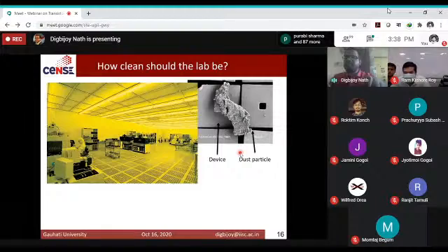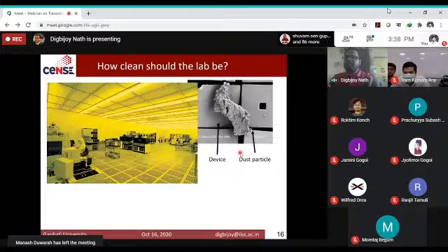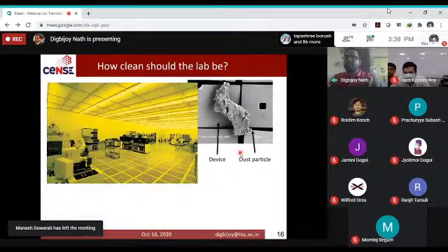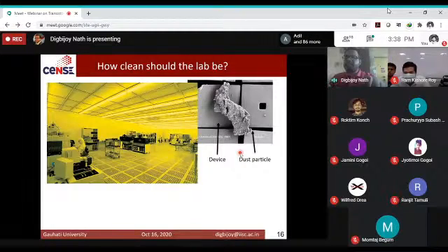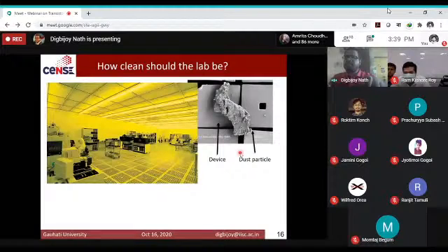That substance is sensitive to photons of higher energy. For example, in visible light, in surrounding sunlight or tube light or bulb, you have light of also higher energy, like the blue component that you cannot see, of course. That will damage those chemicals. That's why you should use a longer wavelength light. Now, red is the longest wavelength light. So ideally you should use a room whose background lighting is red. But then alarms are also red. If there's a fire or some kind of problem is happening, then the alarms have to blink, blink. So the red color has to blink. So yellow is the best light that you can have, such that the material is not sensitive.